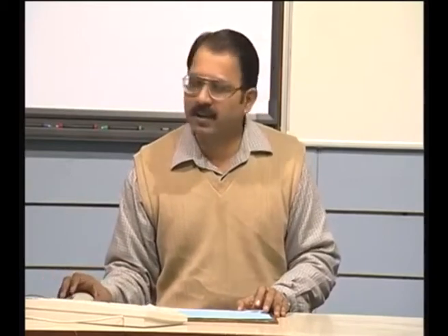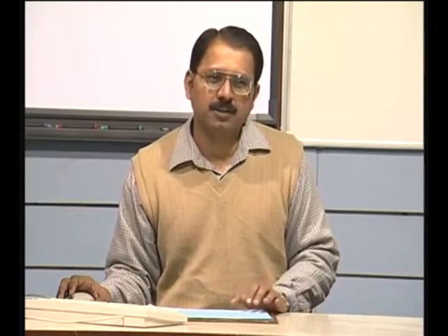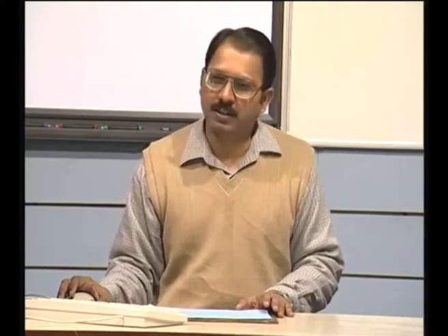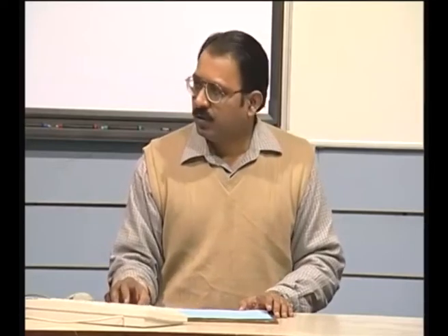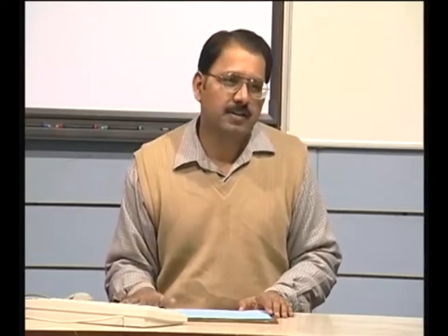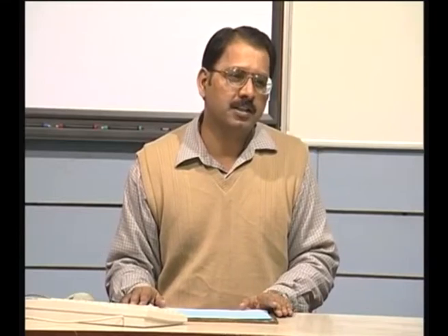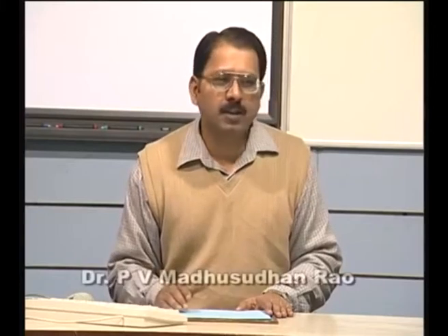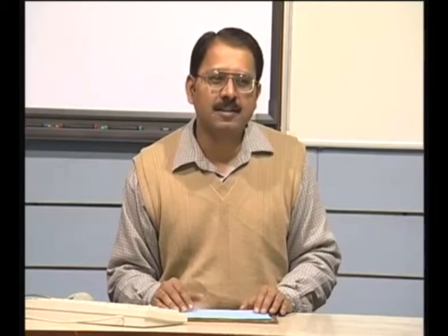So, approximating a curve or a surface as piecewise linear or polygonal is not necessarily for display, it is also true for NC tool path calculation. Here also we see that a parametric representation has an advantage. What I basically try to do in this lecture is to give you enough inputs to convince you that parametric representation is the way to go for CAD/CAM applications, but at the same time we should not undermine the other representations. There are situations where implicit or explicit representations have an advantage.